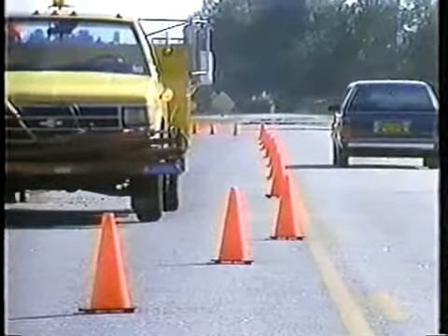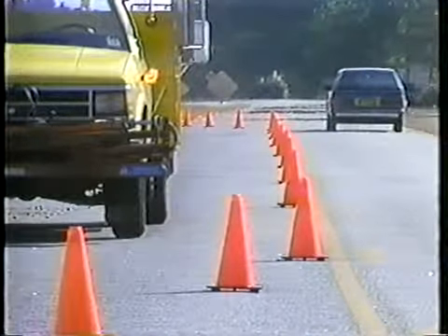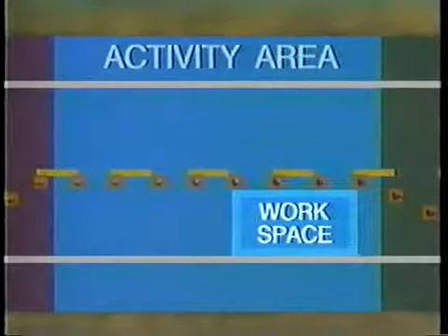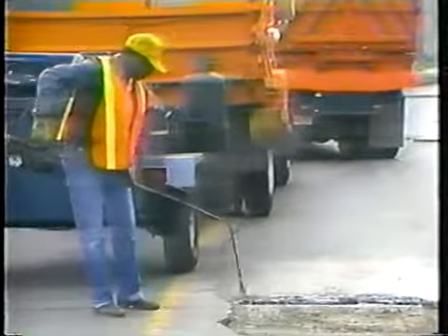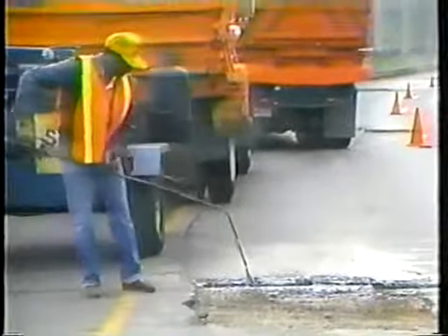The width of this space is determined by engineering judgment and is often governed by the portion of the roadway which is needed to perform the actual work. The workspace is that portion of the roadway which contains the work activity. It is closed to traffic and set aside for exclusive use by workers, equipment, and the storage of construction materials. Workspaces may remain in fixed locations or may move as work progresses. For long-term operations, the workspace may be shielded by barriers to exclude traffic and pedestrians.